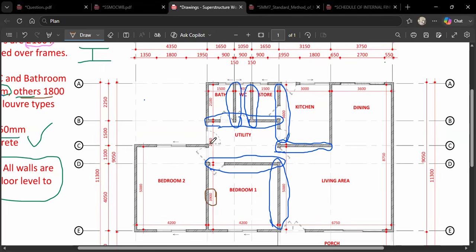And from here to here, from the foundation, there is a block work. It's when you come up before even they come and fix the door. Remember that after the length, the block work will continue. Then we are going to be doing subtraction for the doors and all of that. So we have to take the measurement in full.